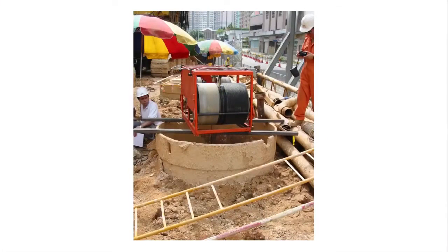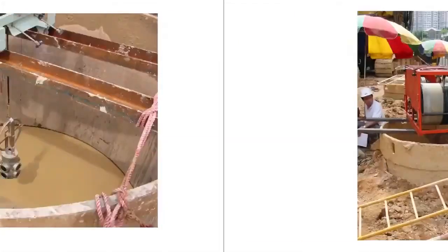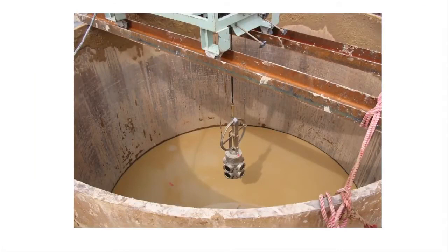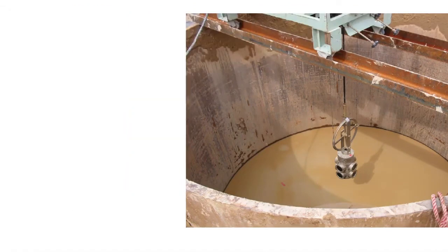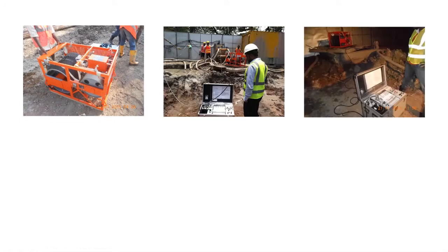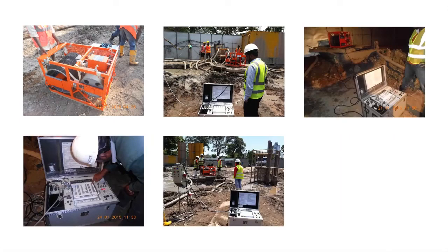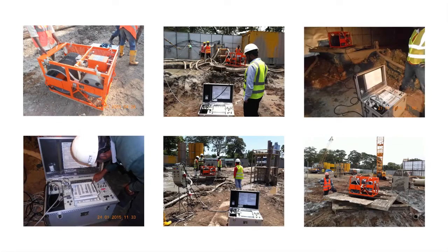The sonic caliper test is performed after washing the pile shaft. Firstly, the winch unit is placed on the center of the pile shaft, and then the sensor unit is moved downwards into the pile shaft at a speed of 4 meters per minute. The sensor unit emits and receives ultrasonic waves while moving downwards and records the waves beginning at the time when the sensor unit emits the signal. The depth and the verticality of the pile shaft are recorded using a digital encoder.